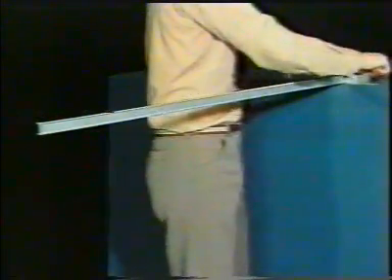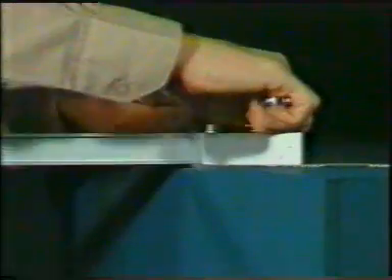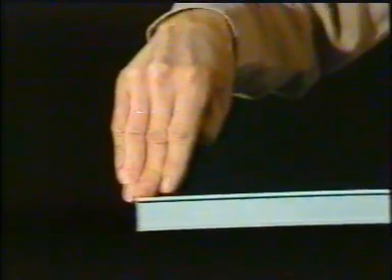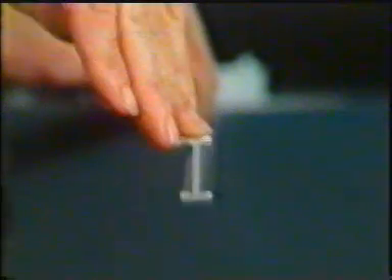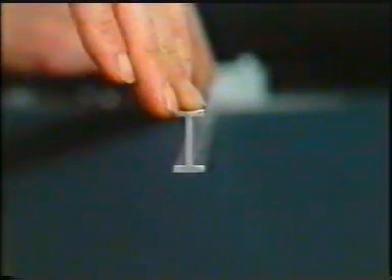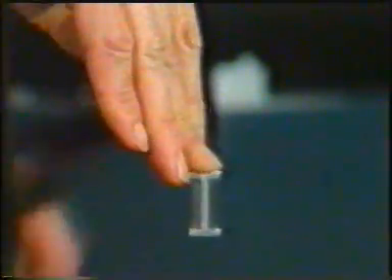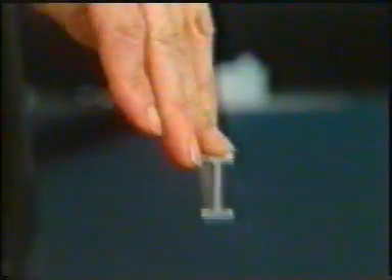Consider a model cantilever with a cross-section of relatively stocky proportions, subject to three distinct actions, which are vertical deflection, horizontal deflection, and twisting. Firstly, observe the response to a vertical load applied at the free end and through the centroid of the cross-section. The end moves downwards, with flexure occurring about the major axis.